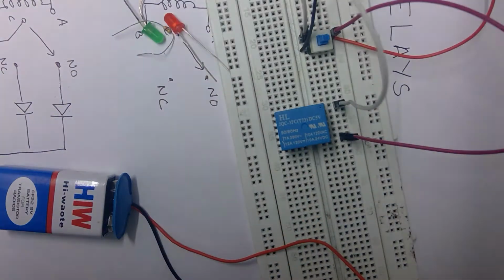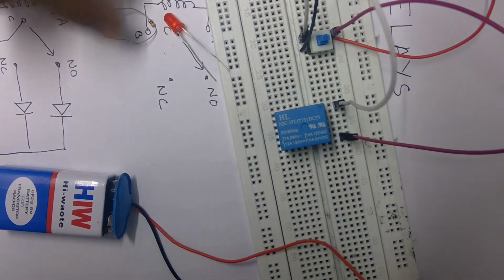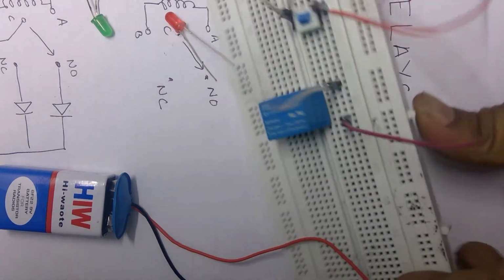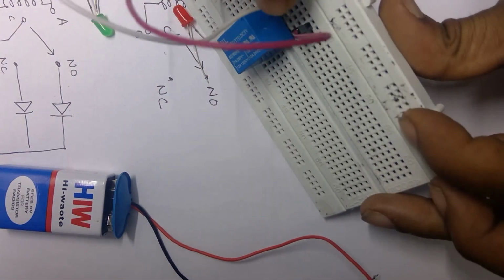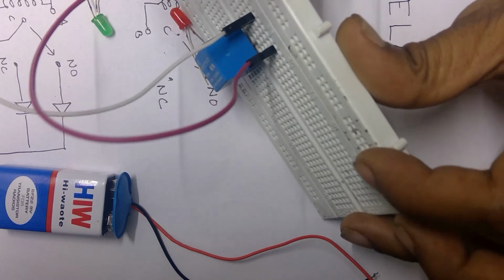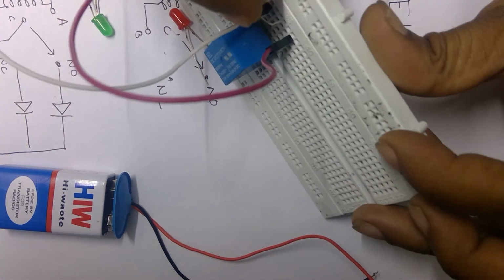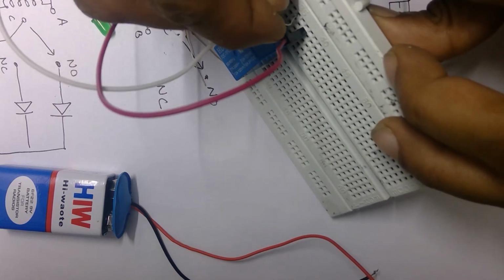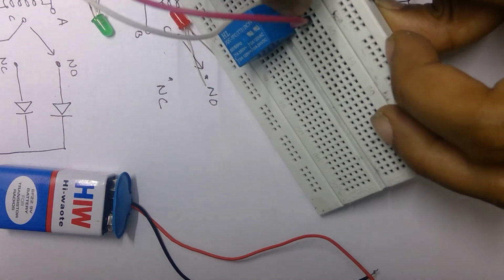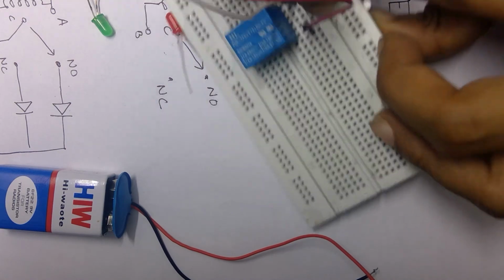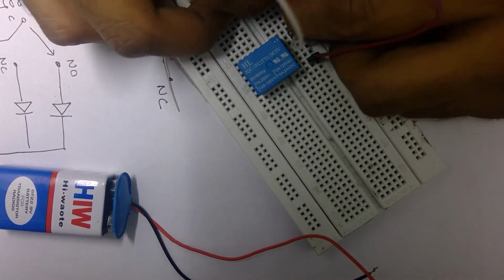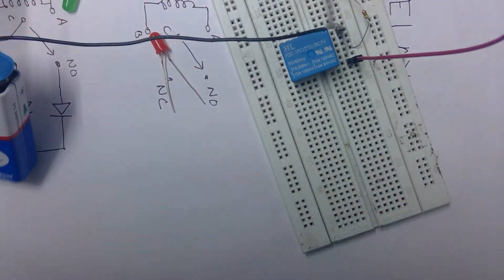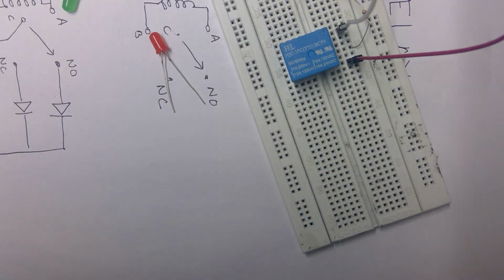Now we need to connect a 5k resistor to the common point, and through that we'll connect a second battery source. This is where keeping a slight gap between the relay helps out, because you can clearly tell on which line I have to put my resistor in. So I put my resistor right here, and to this resistor I connect the positive of my battery power source.